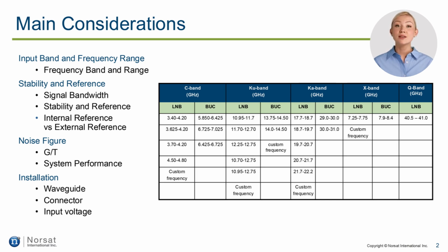The conversion stability is related to how much deviation and oscillation the converted signal has from the desired frequency. To achieve this precision, the LNB requires a reference to make the downconversion from the satellite band to a generic L-band that the satellite equipment uses. The reference is typically a 10 MHz reference signal. There are LNBs that include an internal reference. Depending on the material and the components used, the conversion can have a higher precision than others.